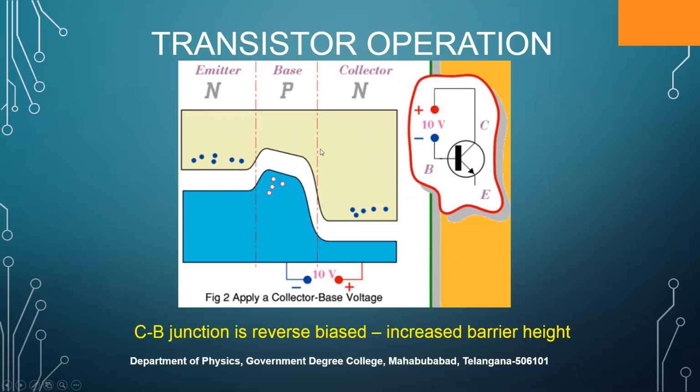That's why the potential or chemical potential of these electrons will be further reduced. That means these electrons can flow easily from this side to this side only when they cross this much barrier. This is a barrier. That's why we always call the base a control switch, that means a switch kind of thing. When these electrons cross this barrier, they can easily move to the collector region.